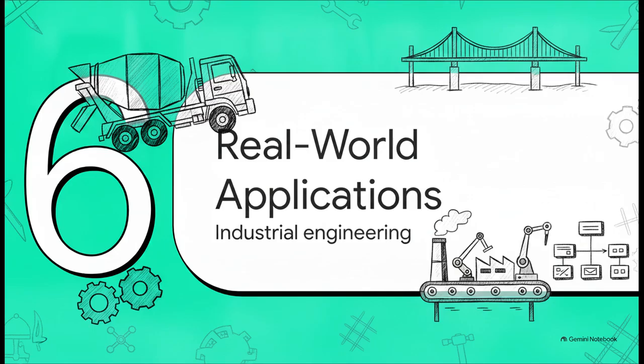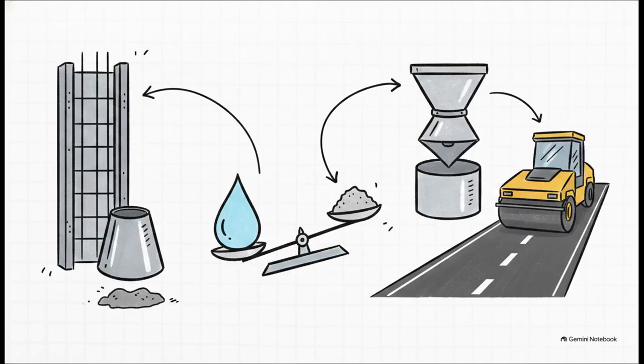Let's tie this all back to the industrial site. Out in the real world, slump testing is what ensures your standard concrete flows easily around all that steel rebar in your everyday walls and columns. But when you are dealing with really complex industrial precast elements or heavy highway pavements, the compacting factor test is what guarantees your stiff mix will actually hit the required density. Both of these tests are absolutely essential.